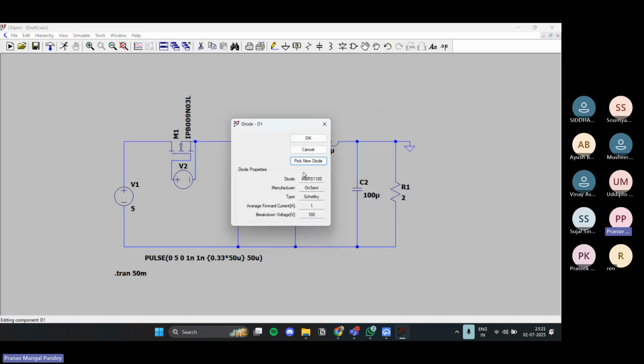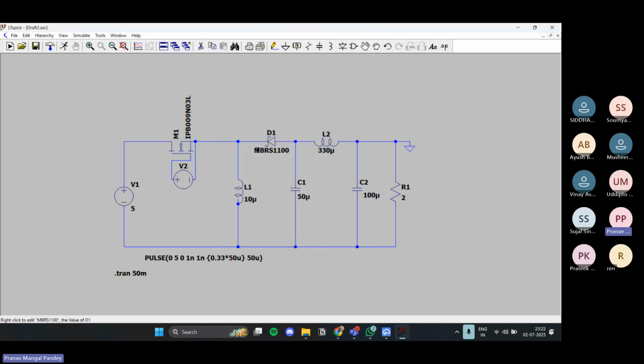For example, the diode I used had a pretty high breakdown voltage, because for a normal diode, I don't want current to flow in reverse bias. In this case I kept the breakdown voltage quite high. If I had tried to use a Zener diode, I would have put a breakdown voltage of around 10 volts or 6.2 volts. So these are some things.